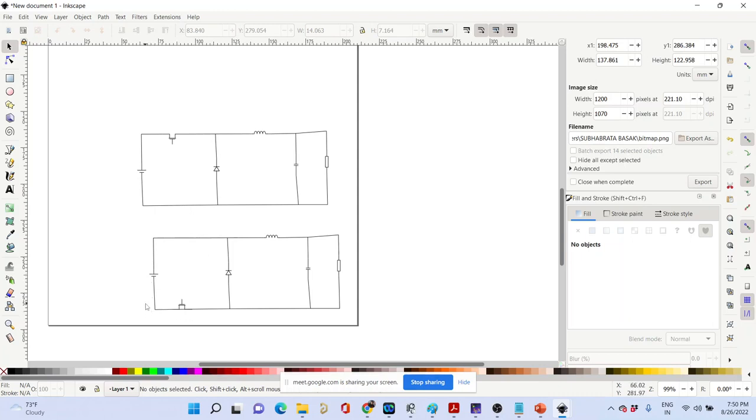So if I consider this as 0 volt, my reference voltage point, whatever voltage you apply, 10 volt maybe, without any confusion you can say that there is 10 volt across this. However, at this point you cannot confidently say that this is 10 volt, because you do not know what potential this point is at. This point may be at 5 volt, it may be at any other potential. In that case, proper turn on of MOSFET would be difficult. Are you getting my point, everyone?